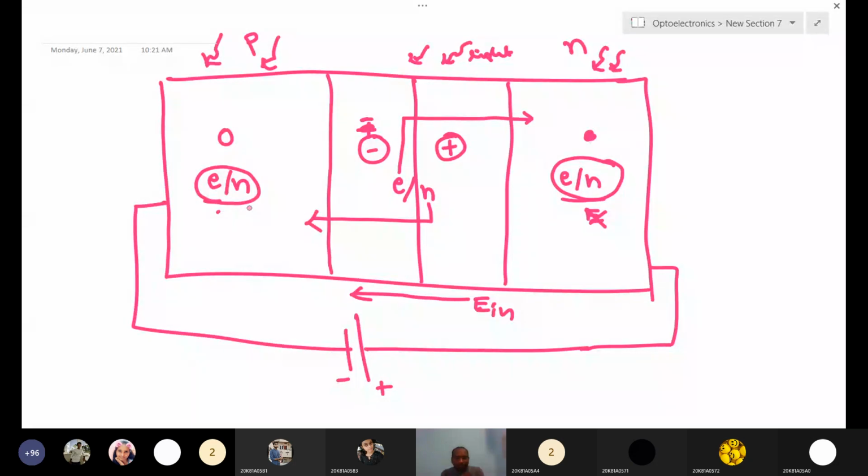Whatever electron-hole pairs are generated in the depletion region are separated by the internal electric field, and are useful for current in a device. That is why the active area of a detector is the depletion region only. Whatever is generated here will be useful for current. These are creating a current in a circuit. So this is the simple working. After separation, we collect these electrons and holes with metal contacts.